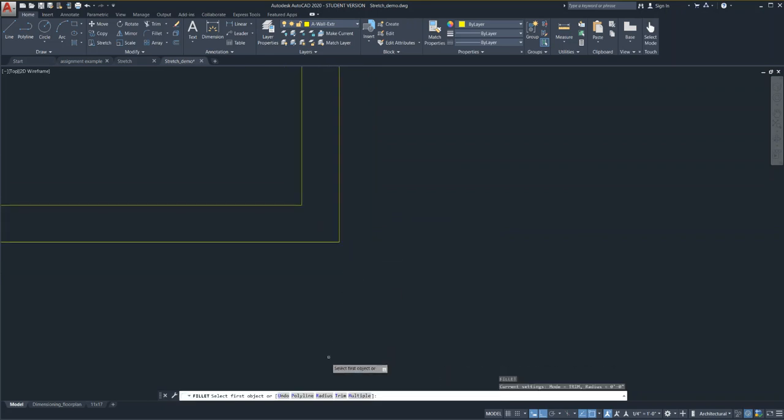F for fillet, radius, 3 inches, enter, there we go. You see it start to round. I think I just didn't tell AutoCAD I was going to input a radius, honestly. Okay, I'm going to hit undo now. F for fillet, enter. I have to pick radius or I type R, enter. Specify the fillet radius. Let's do 6 inches, enter. Click once, click twice, and it's done.